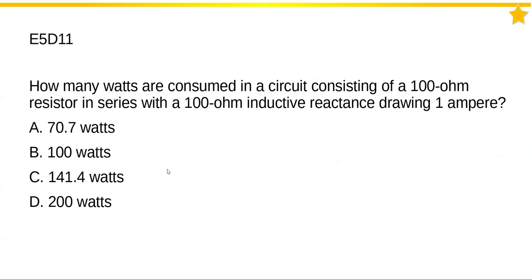How many watts are consumed by a circuit consisting of a 100 ohm resistor in series with a 100 ohm inductive reactance drawing 1 ampere? Nice round numbers. So we're going to have another 45-degree phase angle.